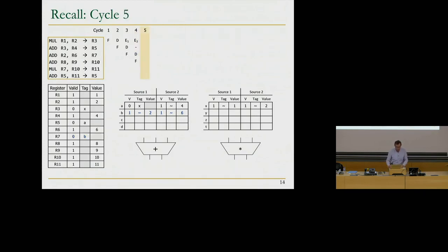In the next cycle, it starts executing, and then the instruction after that gets renamed. And this is an add, so it allocates a reservation station entry over here. Okay, it already did it quickly, sorry. You see that this is also available, it will execute in the next cycle.